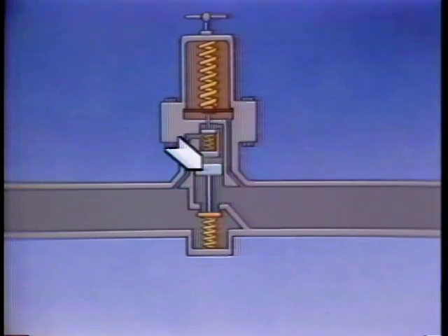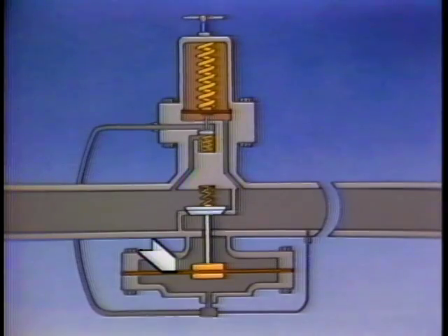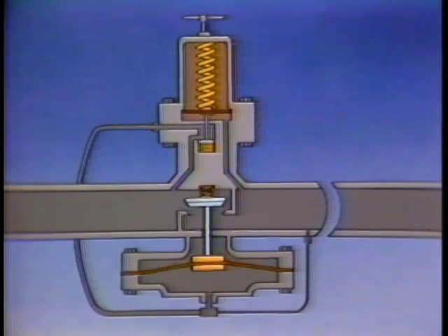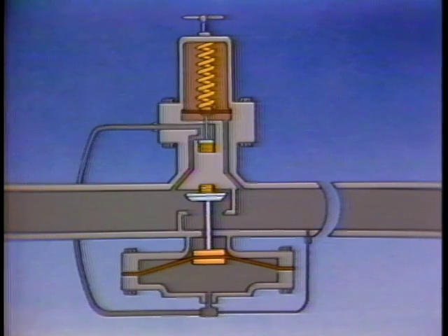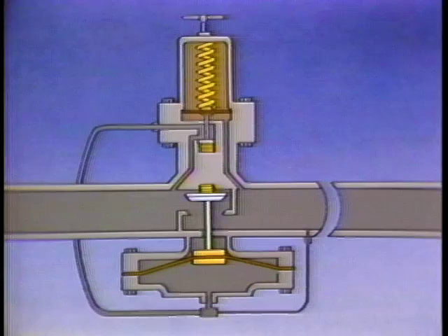An alternative to the piston operator is a diaphragm. A diaphragm can be of much larger area than practical size limitations permit in a piston. Therefore, a diaphragm operator can open a larger valve. The result is greater capacities for a given body size. The PRV works in the same manner as before, but the large diaphragm does present some potential difficulties.